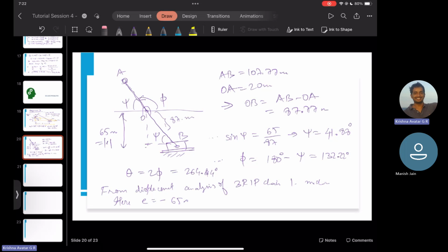And when we have this formula called S2, S is equal to L2 cosine theta 2 plus minus the square root of L3 squared minus L2 sine theta 2 minus E whole square. So this was the function. And we take two values, and in this scenario, since it's coming towards the ground hinge, we'll take only the positive value. So S2 greater than 0 is considered, which is essentially equal to S2 is given as 95.94 mm.